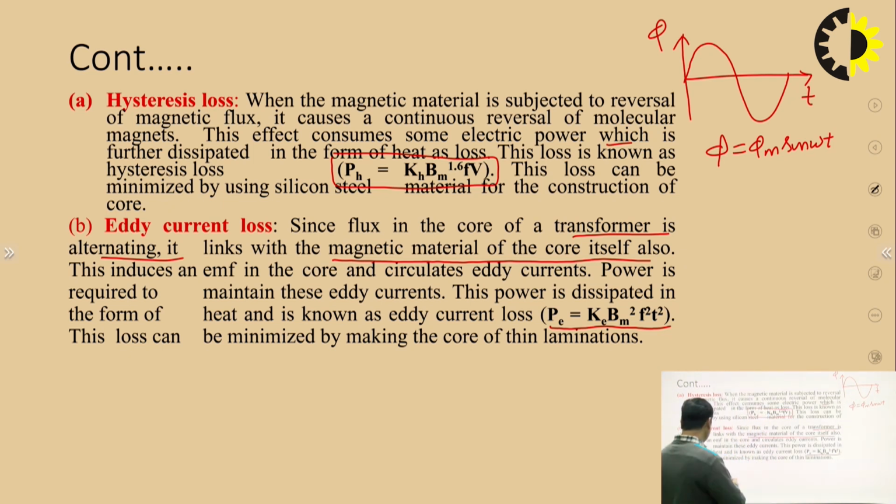These losses can be minimized by making the core of thin laminations. Depending upon the thickness, we can minimize the eddy current losses.